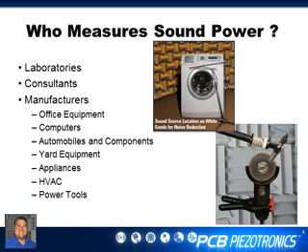So one of the questions you might have now is, who measures sound power? The interesting thing is you can hire somebody to do this. Various laboratories around the world, you could send your equipment to them, and they'll take the measurements on whatever device you have and report the sound power. Consultants will come on site for an in situ measurement if you have equipment that you can't move. They'll perform the sound power measurement on stuff like a stamping machine or forges, anything that's too big to move.